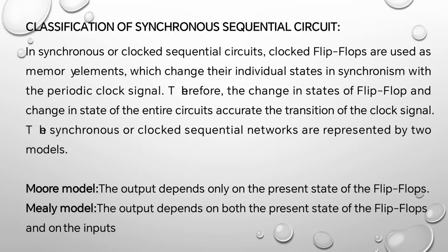First one is the Moore model, second is the Mealy model. In the Moore model, the output depends only on the present state of the flip-flops. In the Mealy model, the output depends on both the present state of the flip-flops and the inputs.